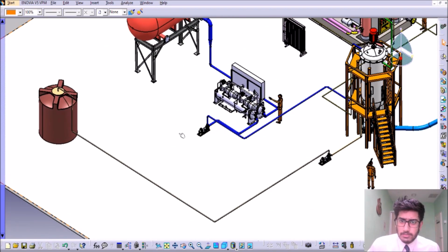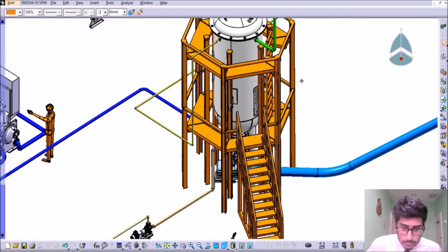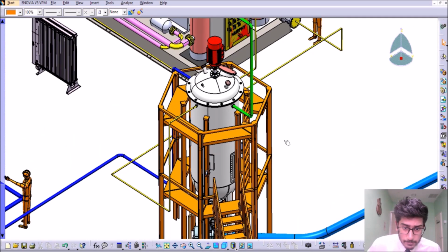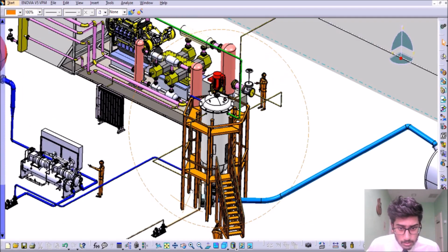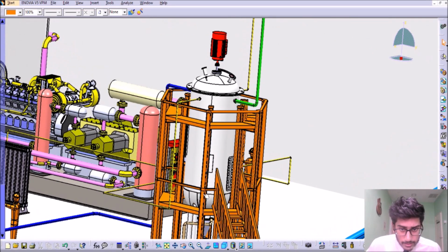So now let's look at the pressure vessel. We can see the motor at the top of the pressure vessel, and at the bottom, let's look in detail, zoom in a bit. Okay, nice. So at the bottom we have the screw injector. This is the drain nozzle, it enters this brown pipe. Then the remaining fluid inside here, when all the water has been drained, enters this screw injector, and then the fluid is pumped into this blue color piping and into the rotary heat dryer.